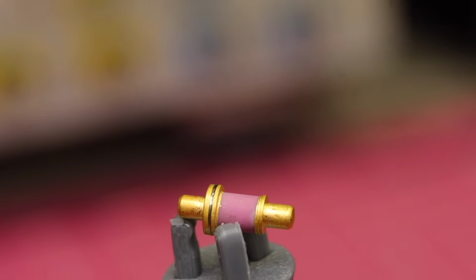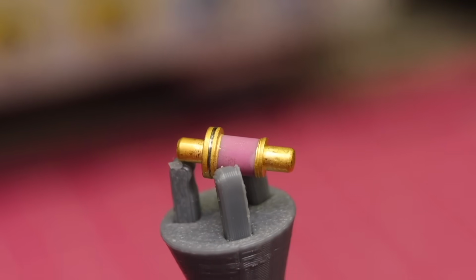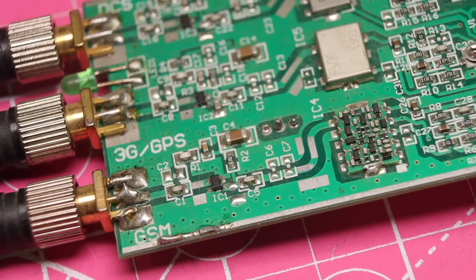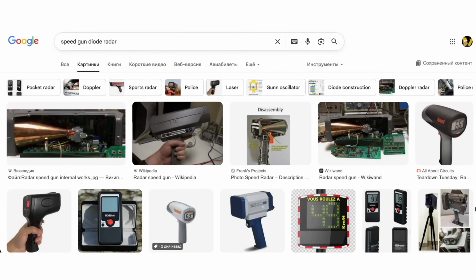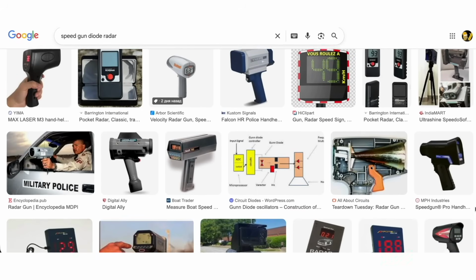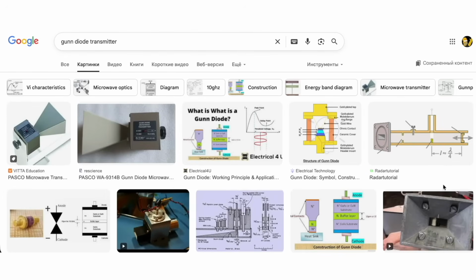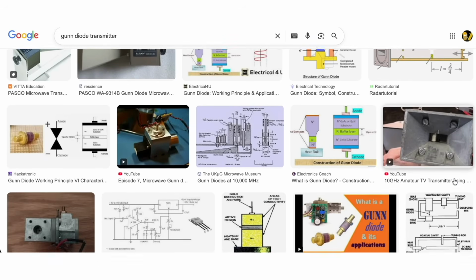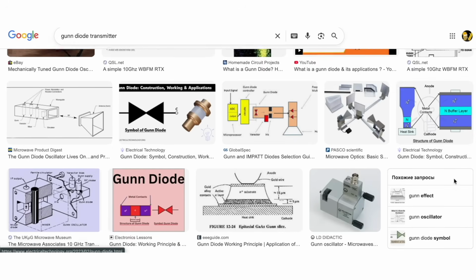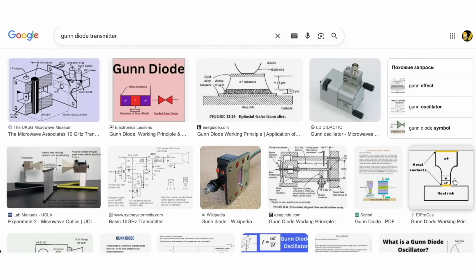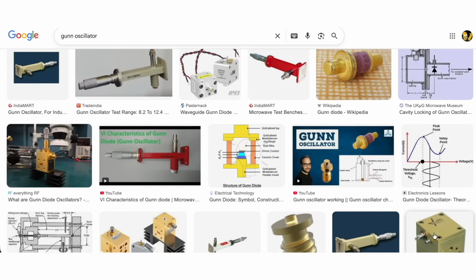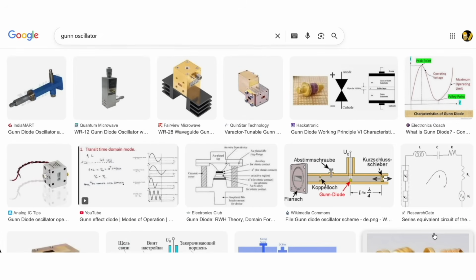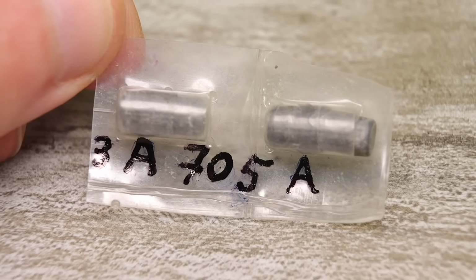So, where are Gunn diodes used in today's world? Gunn diodes are still used in areas where transistor-based oscillators are physically inferior or their implementation is impractical, for a number of reasons. Millimeter wave radars from 35 to 110 GHz, locators at 94 to 140 GHz, spectroscopy and gas analysis, laboratory microwave metrology sources, calibration generators, certain military satellite radar systems, motion and presence sensors. In some measuring instruments, a Gunn diode is used as a reference microwave generator because it provides a sufficiently clean spectrum. Gunn generators are still used in the millimeter wave range.